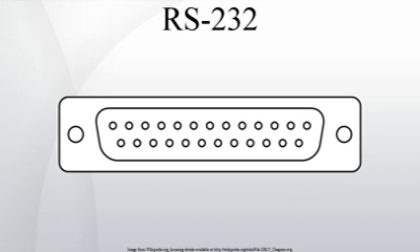USB docking ports are available which can provide connectors for a keyboard, mouse, one or more serial ports, and one or more parallel ports. Corresponding device drivers are required for each USB-connected device to allow programs to access these USB-connected devices as if they were the original directly connected peripherals. Devices that convert USB to RS-232 may not work with all software on all personal computers and may cause a reduction in bandwidth along with higher latency.